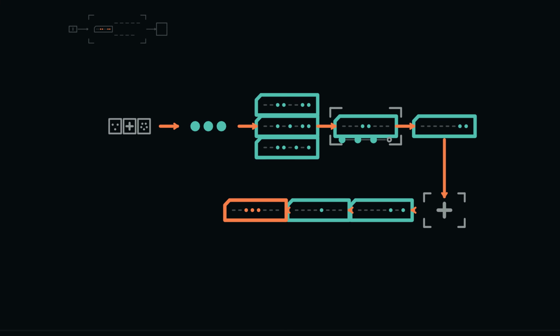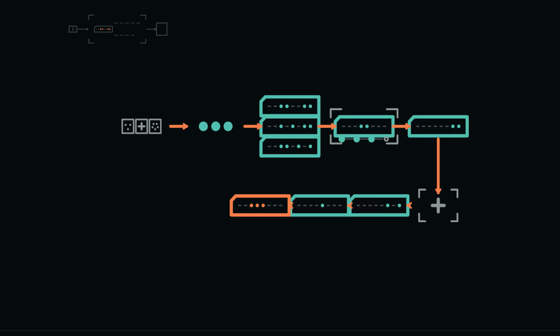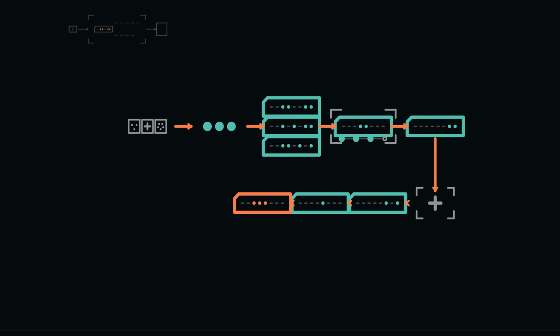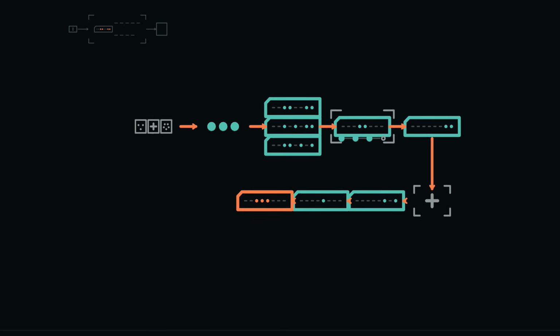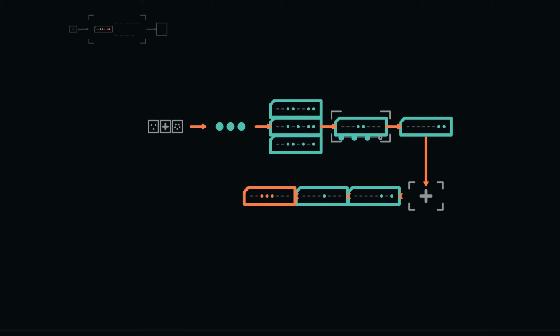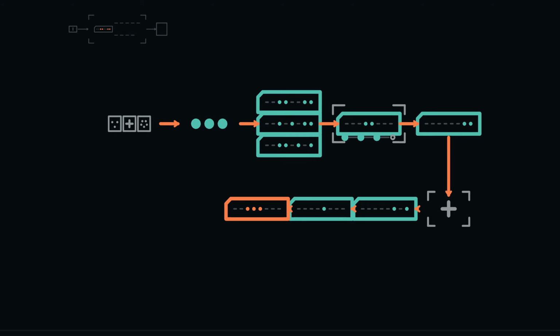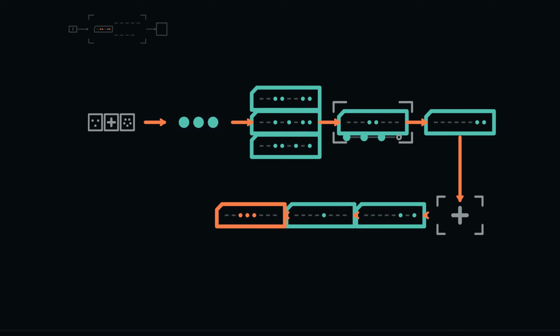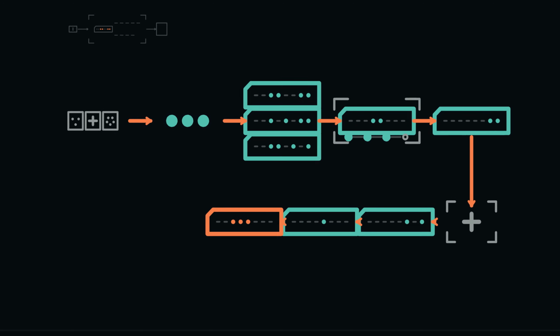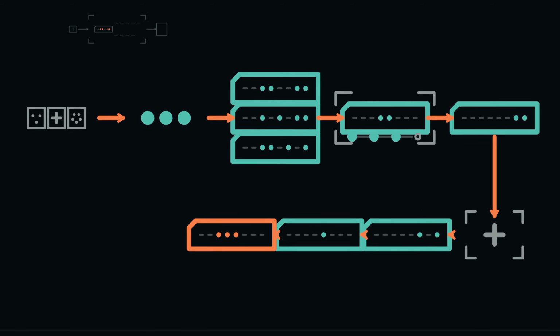The store instruction places address F3 in the memory address register and hexadecimal 38 in the memory data register. On the right edge, the decoder activates the display data register, not RAM, and the adapter accepts the byte. The simulator records 1 output event with decimal value 56. The processor's job in this transaction ends at that committed interface. It has supplied a code, it has not drawn a line, chosen a typeface, or illuminated a pixel.